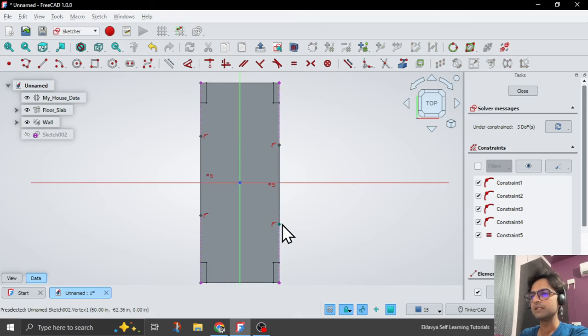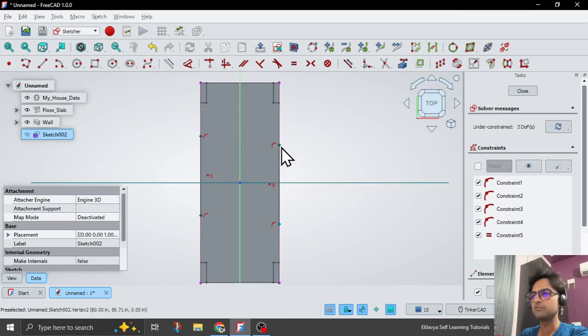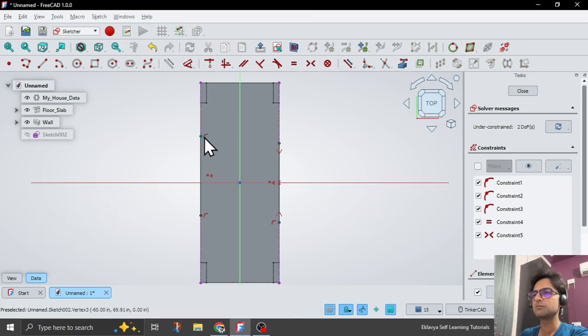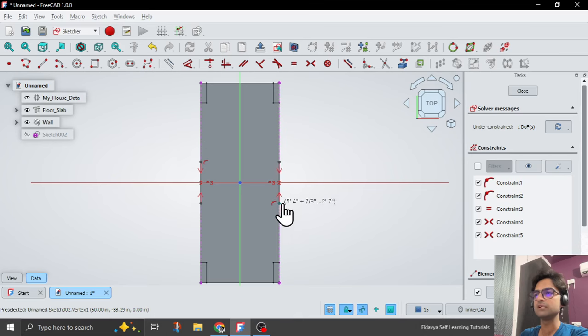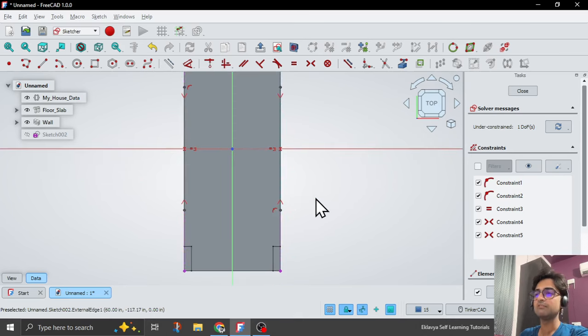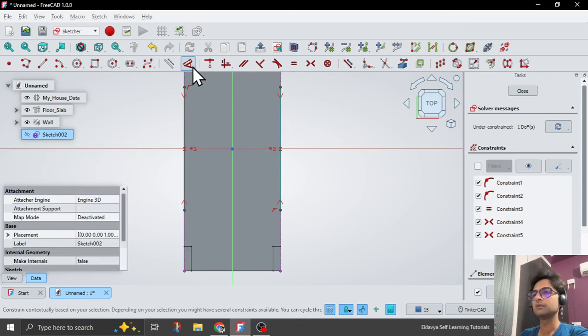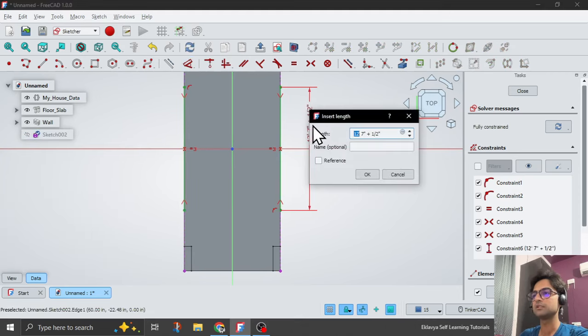and then let's make them constraint equal with the x-axis of this sketch. Similarly for this one, right? So now they will increase or decrease evenly. And now basically I will add the dimension here, which was the curtain wall length. So click on this and dimension here,